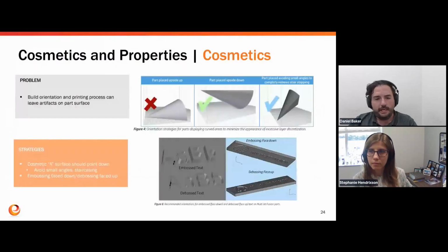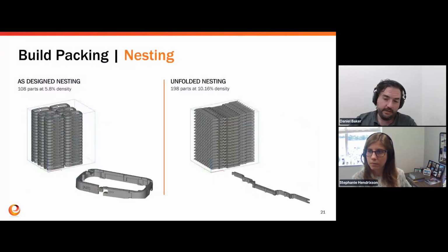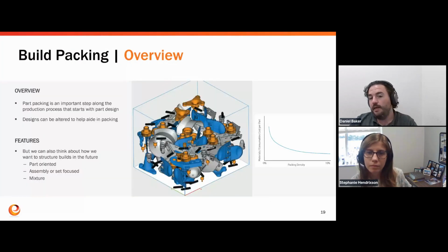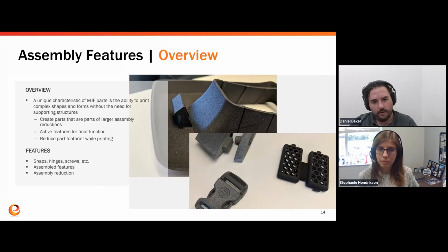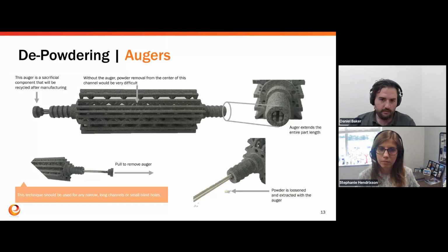If you're looking at any specific additive part and you're considering a powder bed method, whether it's HP's Multi Jet Fusion, SLS, anything with powder involved, you're going to really want to control your blind holes or any kind of cavity within your part. It even goes into, take a generic housing, something like your phone case.